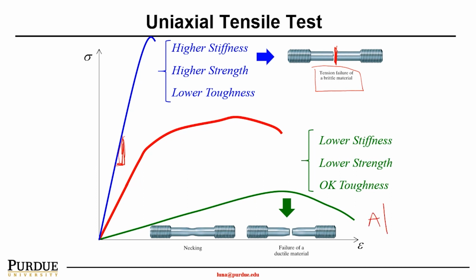So if I have a piece of aluminum material with the same shape as the carbon fiber, when I'm doing the uniaxial tensile testing, I would expect it to start to develop a neck area, and then eventually fail. And as you can see here, the deformation of the sample has been substantial. Rather, in contrast, there is very, very small or marginal deformation.